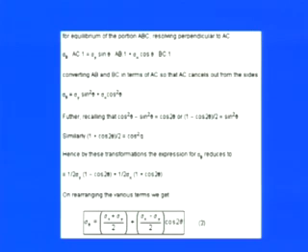We have the final stress at the oblique plane in the normal direction: sigma theta equals (sigma x plus sigma y) by 2, which is not influenced by any theta. This is a constant quantity. So one term is constant and one is influenced by theta: (sigma x plus sigma y) by 2 plus (sigma x minus sigma y) by 2 into cos of 2 theta.